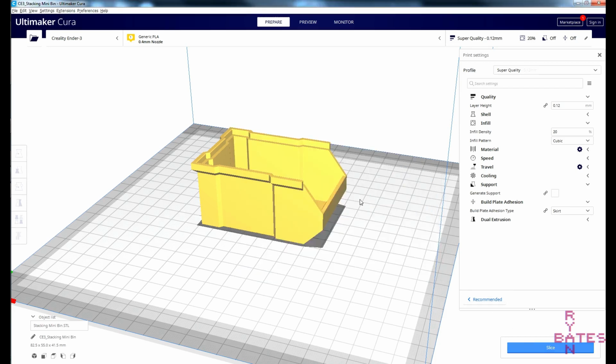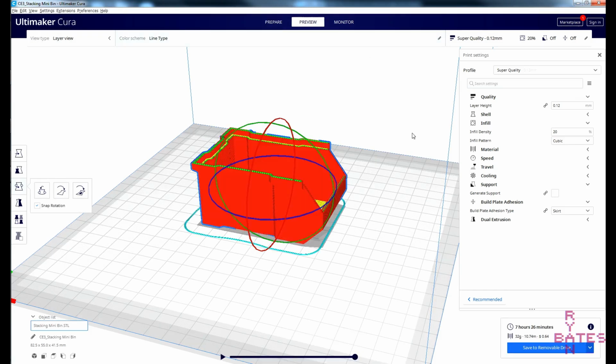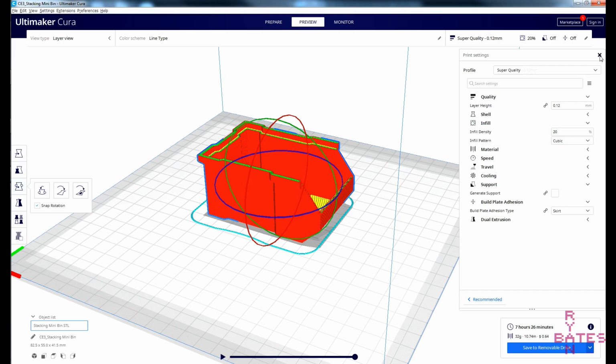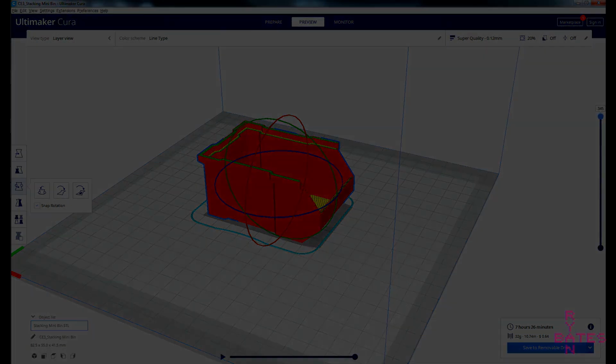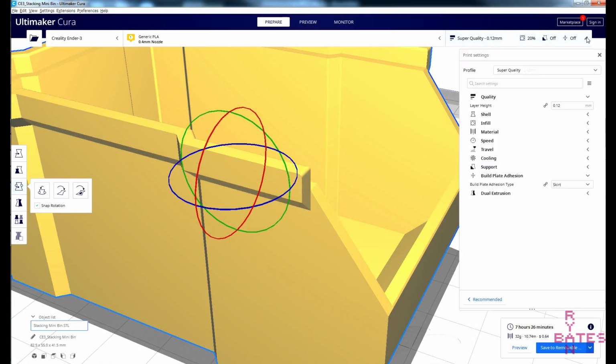If you want a stronger part, it will cost you more in filament resources, become heavier, and again, may take longer to print. Just a general reminder, the more you deviate from recommended settings, the further away you may deviate from a successful print. Let's focus on our first trait, print quality.